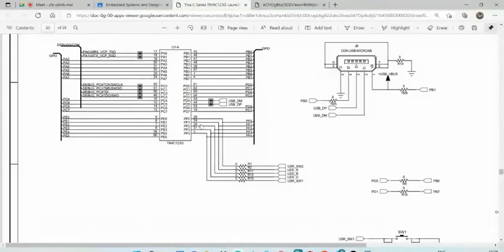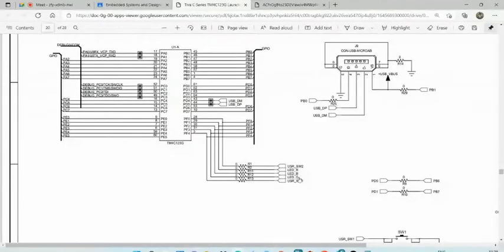So it is connected here in port F, the LEDs. Okay, note these numbers. PF0 is connected to user switch 2. Note it somewhere on a page, preferably, so that you can practice writing also. It is not that good engineers don't use pages; they use more pages. Anyway, PF1 to LED red, PF2 to LED blue, PF3 to LED green, and PF4 to user switch 1. Make a note of this.